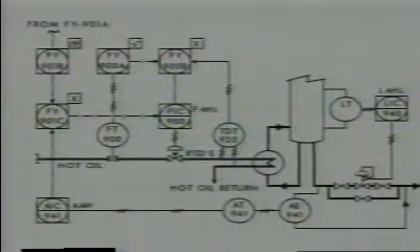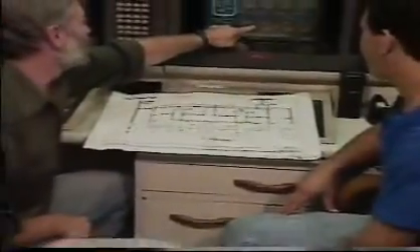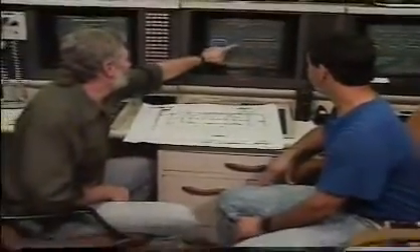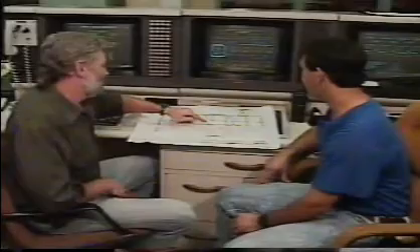You'll also see other symbols on the P&ID, such as those for the primary element and final control element. The primary element, or sensor, is the part of the loop or instrument that first senses the value of a process variable to determine an output signal. The final control element directly controls the value of the variable of a control loop. Usually, the final control element is a control valve. Your workbook contains additional information about primary element and final control elements and the other symbols discussed in this segment.